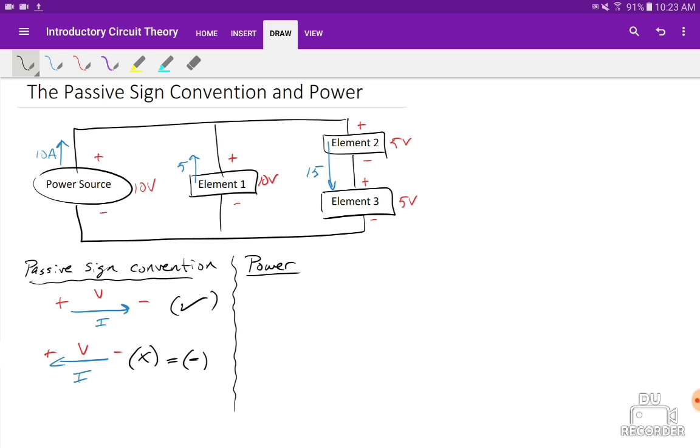The equations, once you've solved them, are going to tell you, oh yeah, this solves to be negative, which means that the direction as seen on the circuit is not the end all be all. It may actually not be that way. A lot of times your answers are going to be negative because your professors have built your circuits and described the directions of your voltage and current in specific ways. So what I'm trying to tell you is what you see is not always exactly what's happening.